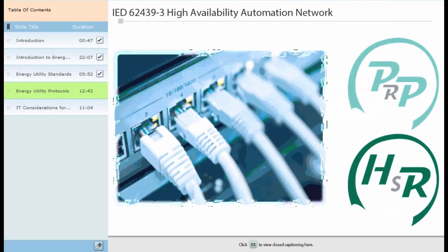Redundancy provides the feature of transparent resiliency. In modern power substations, redundancy is a paramount necessity for Ethernet communication because downtime causes serious consequences, even in the event of a switch or cable failure. The IEC 61850 standard uses two main redundancy protocols selected for substation automation, which are described in the document IEC 62439-3. These include Parallel Redundancy Protocol, or PRP, and High Availability Seamless Redundancy, or HSR.